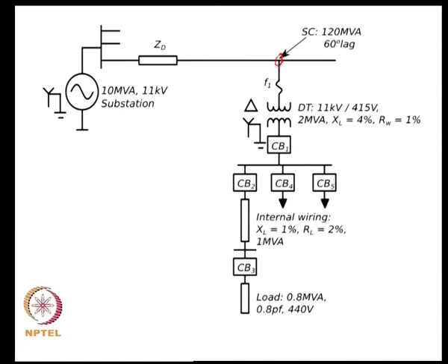So, when someone says it is 120 MVA, that represents the product of the fault current and the nominal voltage of the system, and to evaluate what the short circuit capacity at that particular point is, the utilities can actually provide it to you, especially when you are connecting large systems. This would be an important aspect of the information that you would need for sizing the interconnection. Okay.